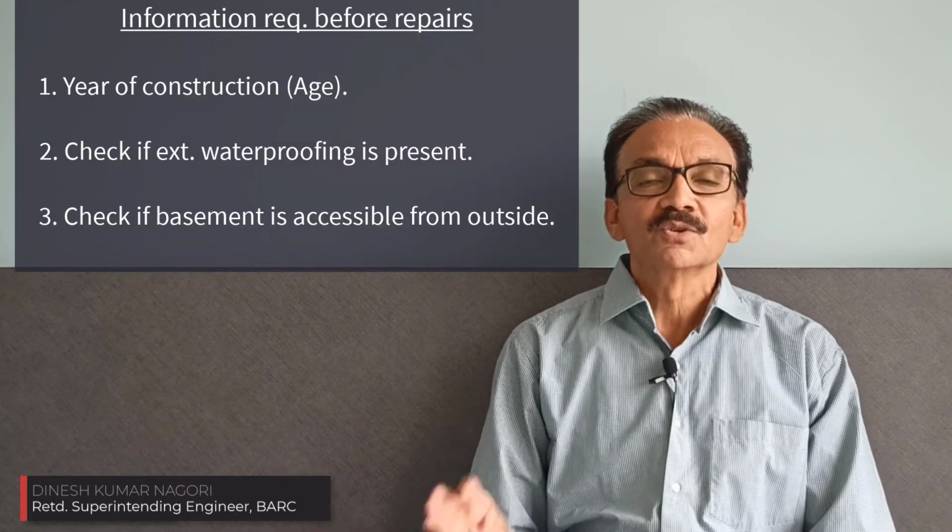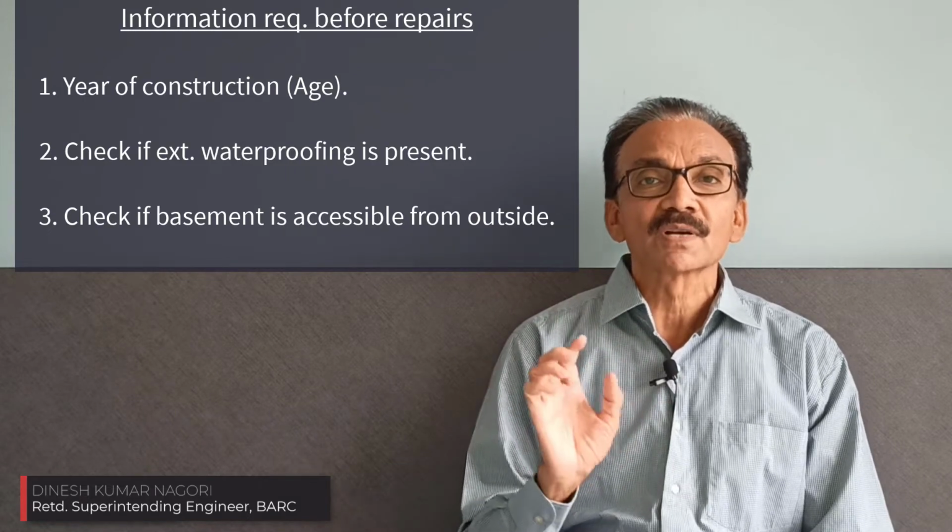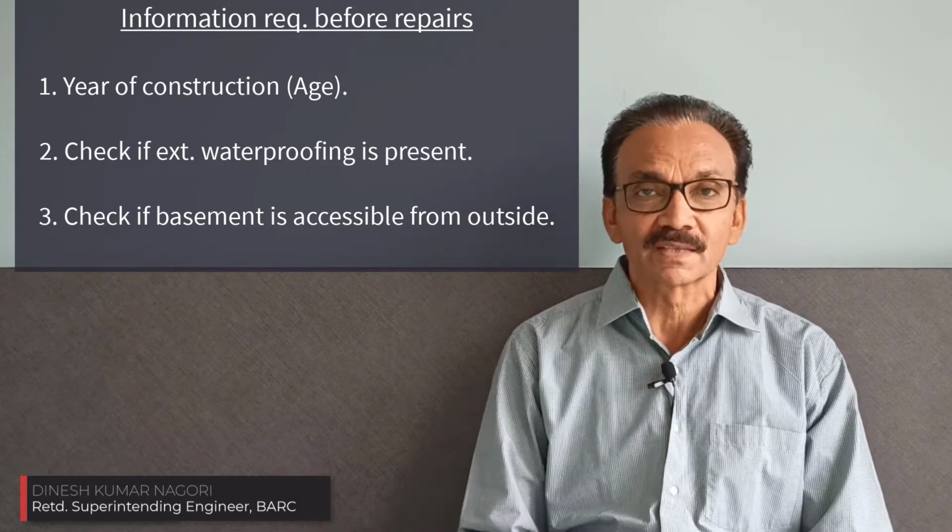Now suppose, coming back to the problem of leakages in the existing basement. So it is a very difficult situation because already the basement is in use. See, either it must be in use as a parking or there may be some shops or some godowns. So at that time that repair becomes difficult. So before you start the repair work, see, some information is required. First of all, you have to check when it was constructed and whether external waterproofing was done properly or not, if you can get this data.